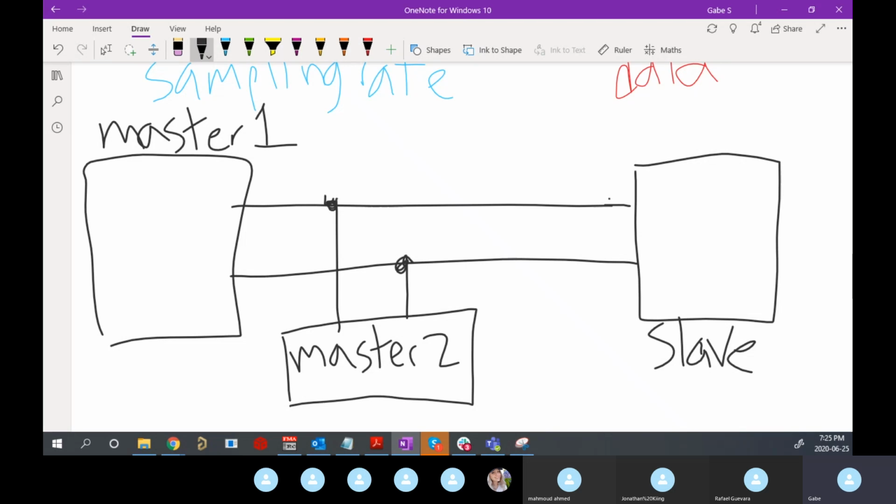Thoughts on I2C? I think it's good. I think it's a useful protocol, especially if you're limited on pin count. Let's say you have a wireless device or maybe a wearable you've designed, and it needs to operate as a little tiny device. You're probably using an 8-bit microcontroller, something really small with low power, and maybe there's only like 16 pins on that chip, right?